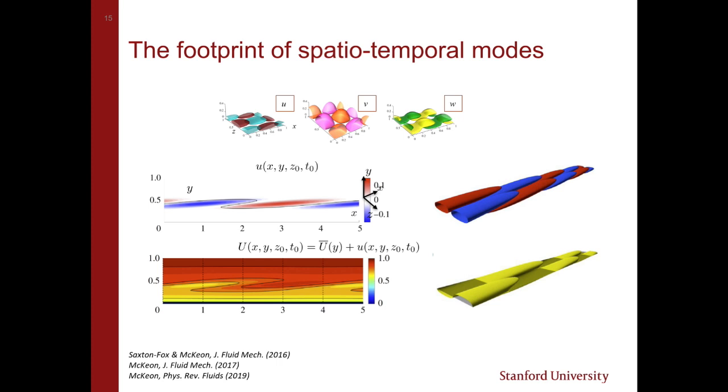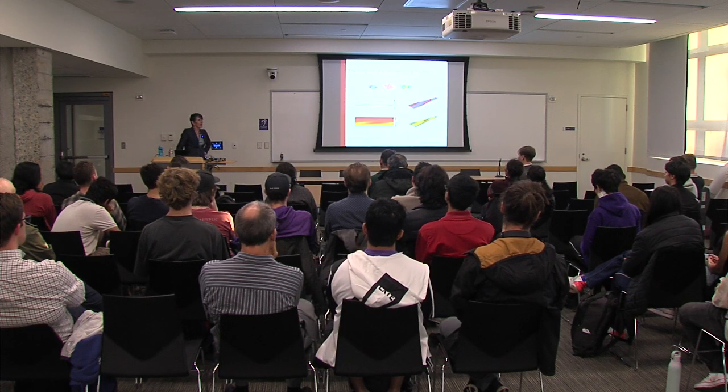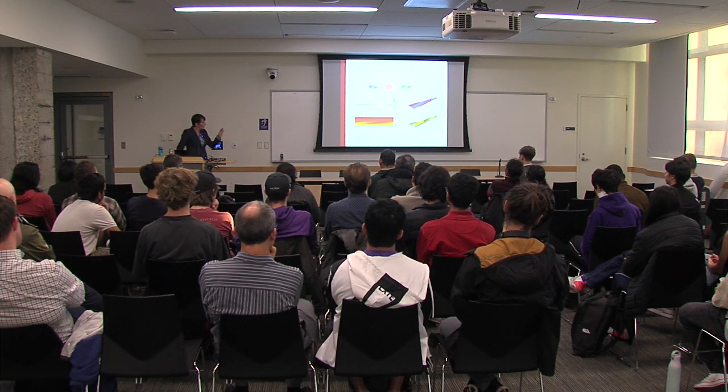It goes up in an asymmetric way to the way it goes down because I have a shear profile in here. This is just what happens when you sum these two. Those of you who've looked at turbulent flows will recognize some familiarity in the turbulent bulges that you see a lot in wall turbulence. Again, without specifying the relative magnitudes, that kind of bulging shape has a very simple origin in the type of mode that has, in this instance, a Gaussian amplitude variation and a linear phase. So you get that bulge as a natural outcome.